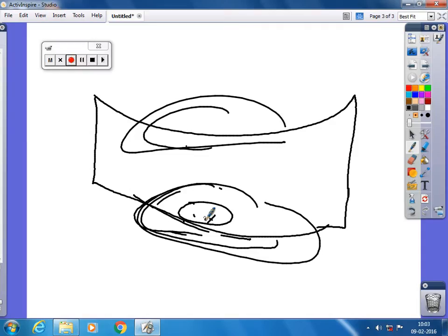What did I say now? It is weak where? In the bottom. So when a knot is formed in the bottom zone, that is in the tension zone, what happens? It weakens and reduces the strength. But if it forms in the top of the beam, the weakening is less.